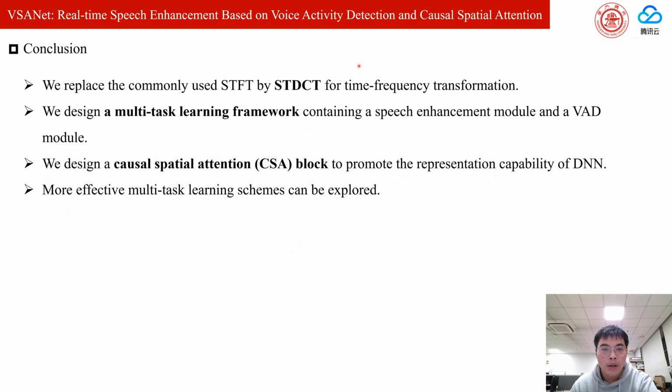In conclusion, we replaced the commonly used STFT by ST-DCT for time-frequency transformation. We designed a multitask learning framework containing a speech enhancement module and a VAD module. In addition, we designed a causal spatial attention block to promote the representation capability of DNN. In the future, we plan to explore even more effective multitask learning schemes.